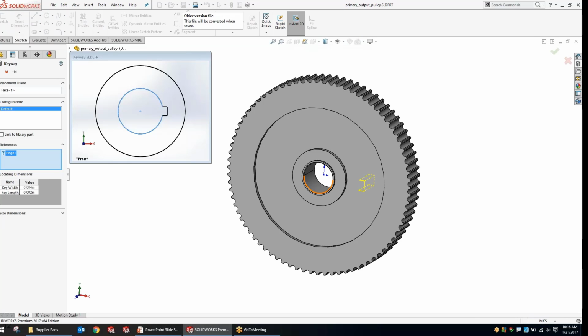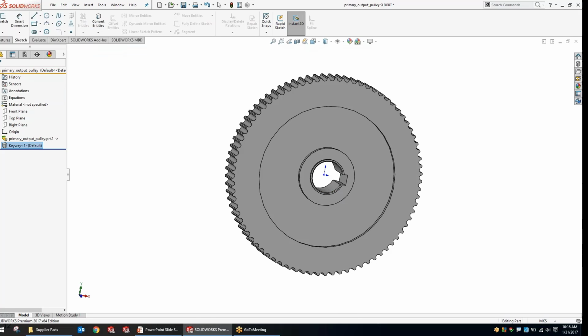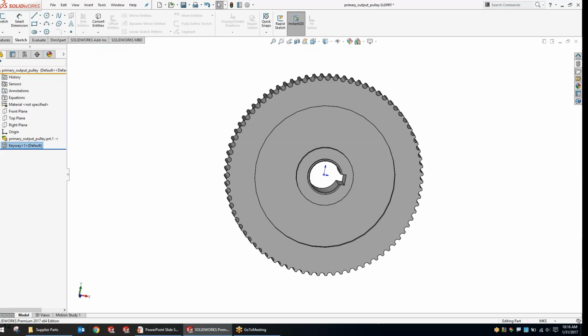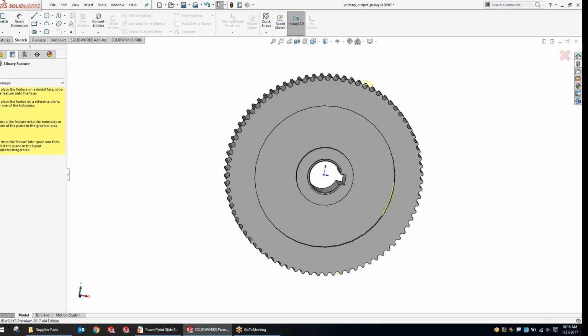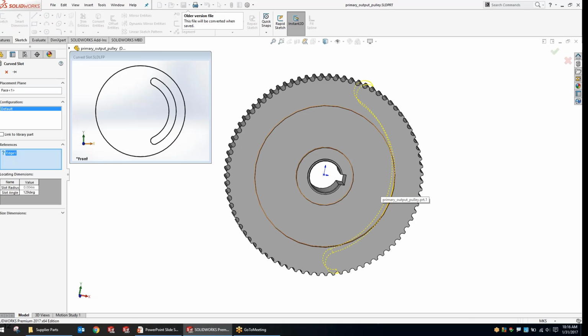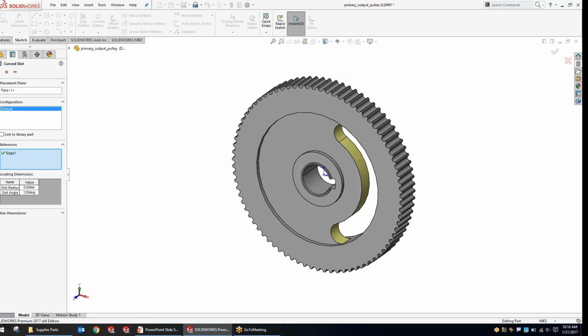And the key to notice with this, using the design library, is that we're locating faces and edges. And this is something throughout SolidWorks 2017, not just 3D Interconnect, but the improved process for working with face and edge IDs, even with just regular SolidWorks parts, has improved drastically to where now even with SolidWorks parts, when you do a convert to bodies function, or when you save an assembly out as a multi-body part, those face and edge IDs are going to be preserved.